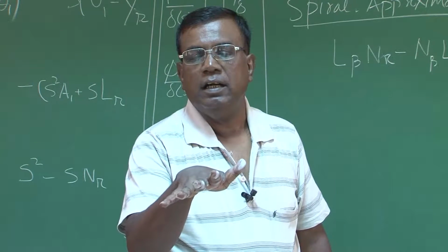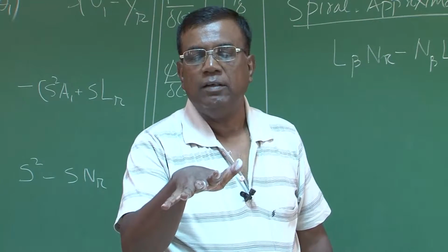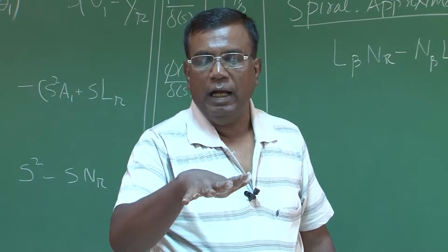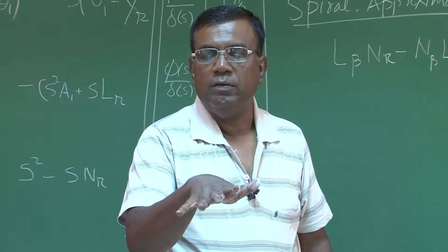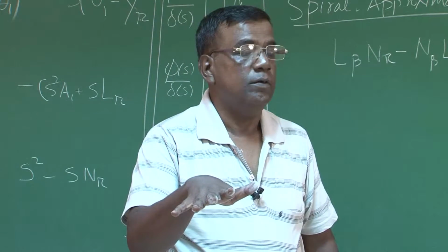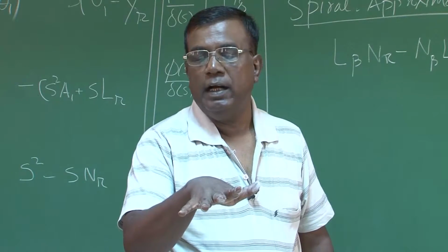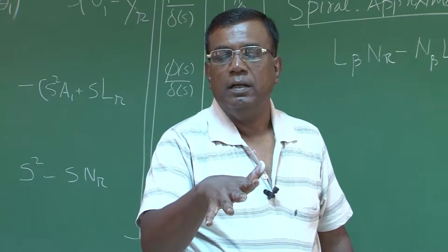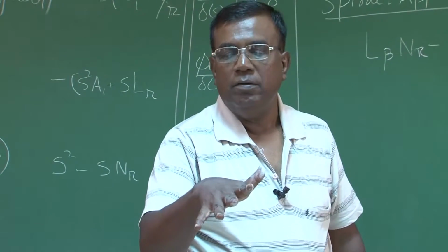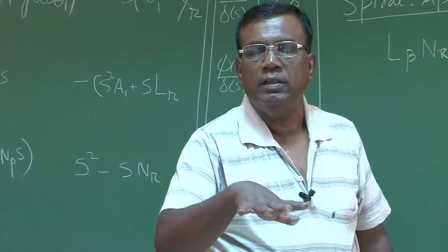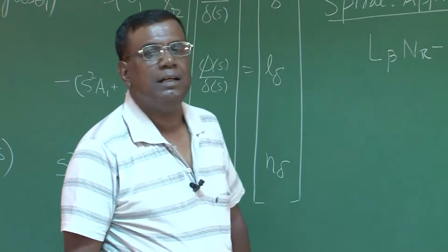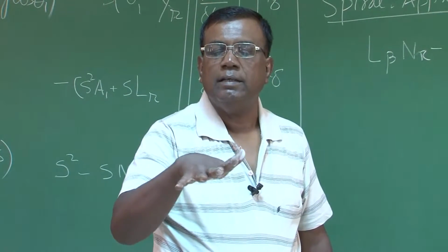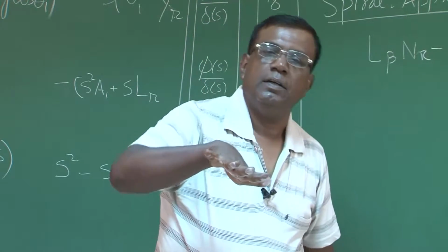As it turns, there is a yaw rate R that will also give a rolling moment, because the vertical tail is pushing the air towards my left hand side, so it gets a force on the right hand side, which further banks the airplane, and then further there is a beta, further there will be turning. This combination will go on unless you have CL beta, that is, as it banks and side slips, CL beta tries to recover it, right?